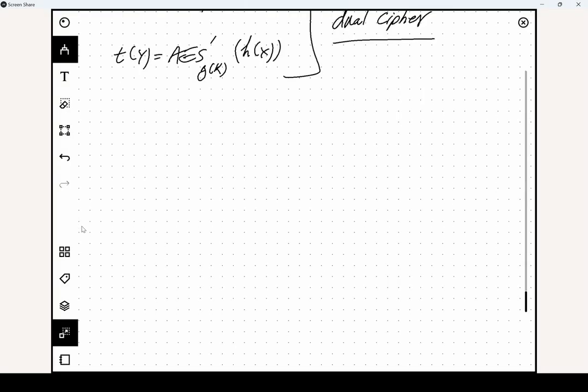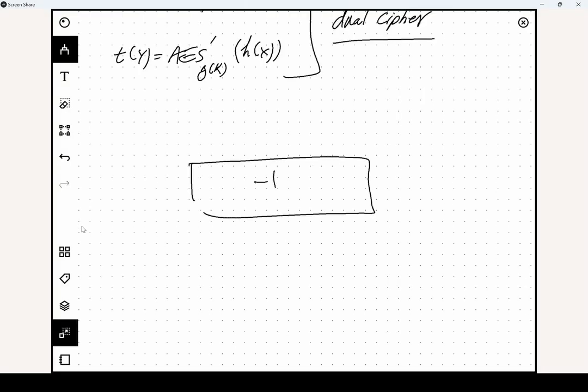You need to tell the synthesizer that you need NAND gates instead of AND gates, and then invert the input of the XOR gates. But what Canright did, which is a nice way, is that you have the inversion, and then for the Sbox we said that you have the affine transformation, and this is the normal way. But then if you want to implement the inverse of the Sbox, then you need the affine inverse. You have to give the input to the inverse of the affine before giving it to the inversion.